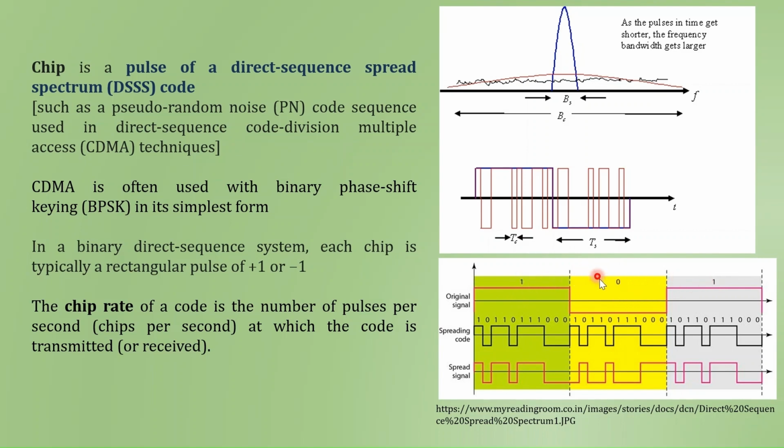1. So to have the simplification, we use binary phase shift keying. Binary phase means we are having two phases. So we can see here that this particular phase is utilized for the 1, and for 0 we are changing the phase. Originally it was starting from the upper mark, but by changing the phase now it is in continuation. So this is referred to as binary phase shift keying, meaning wherever we are having the alternate values we are changing the phase of the wave.